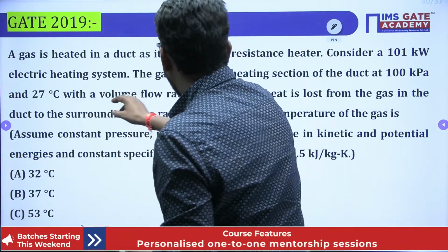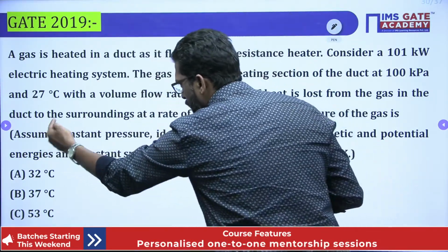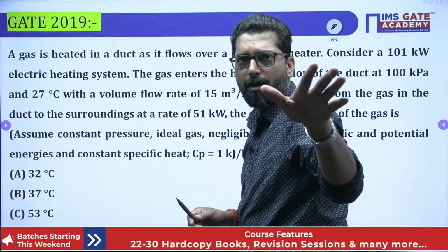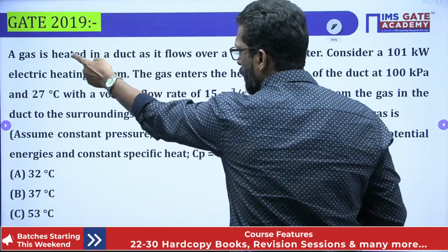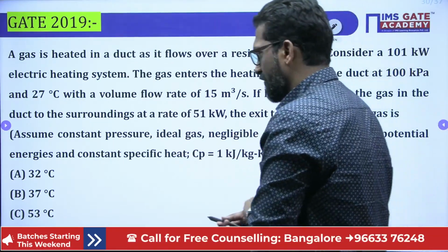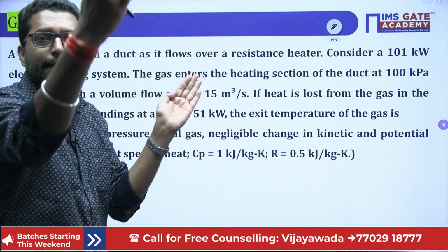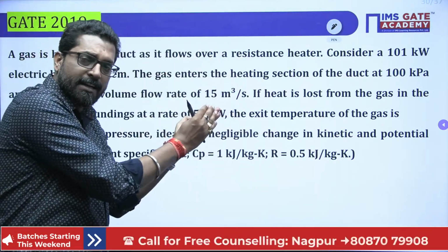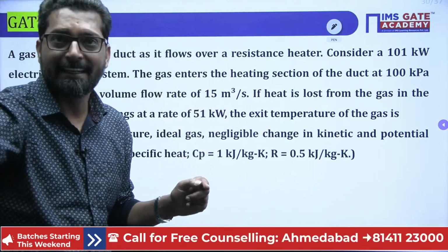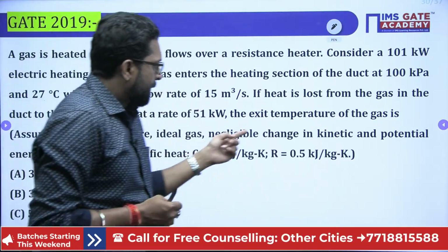Now, what we can do is that during the heating process, heating through the resistance, this has a constant pressure. No problem at all. Okay, the gas we assume is an ideal gas. Negligible change in kinetic and potential energy, that means the inlet kinetic energy is the same as the exit kinetic energy, and the inlet potential energy is the same as the exit potential energy. That means the change in potential energy and change in kinetic energy is zero. That means the system is stationary. Okay, no problem at all. Negligible change in kinetic and potential energy.